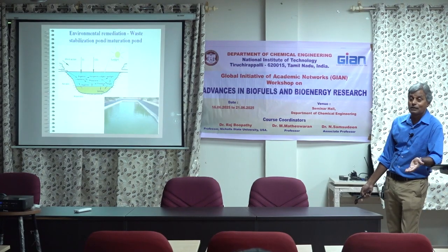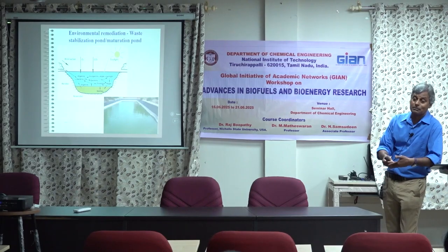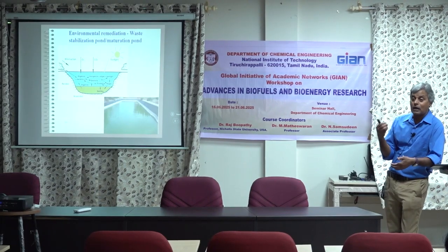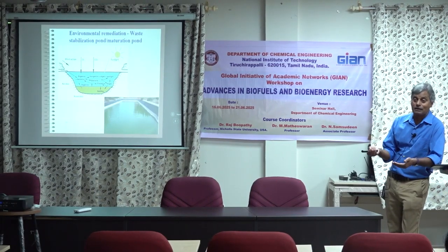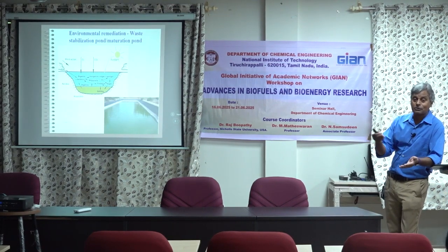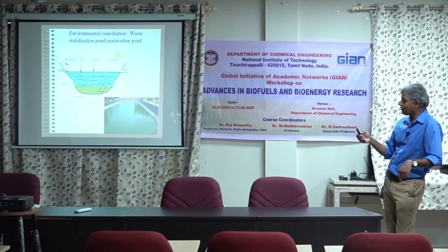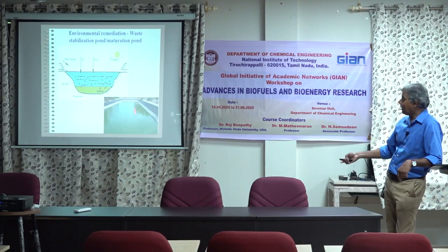the wastewater. So this is greatly used in the wastewater treatment system as an oxygen supplier to bacteria, because during photosynthesis, these algae produce oxygen that could be used by aerobic bacteria to break down organic carbon. Okay. So there's an example here of an algal grown wastewater treatment system, so you don't have to pump oxygen into this process.